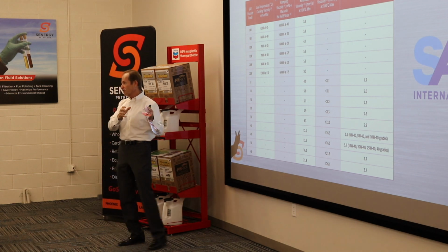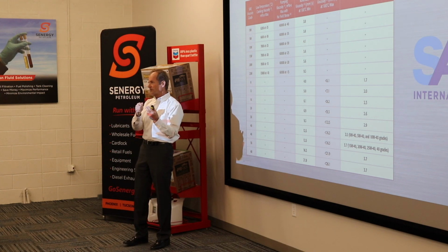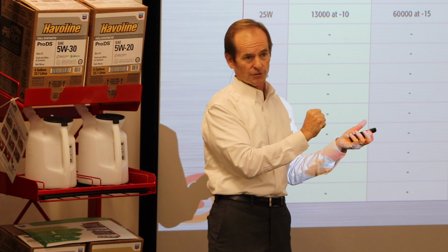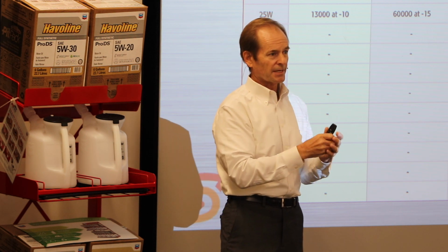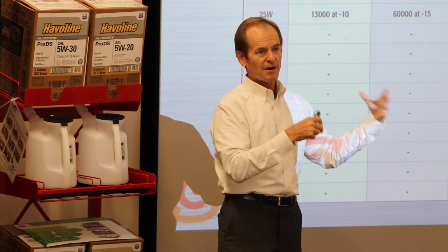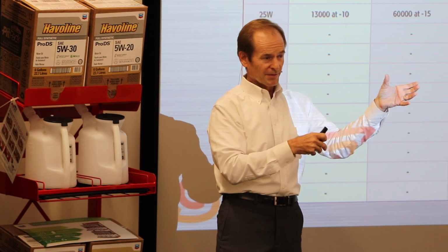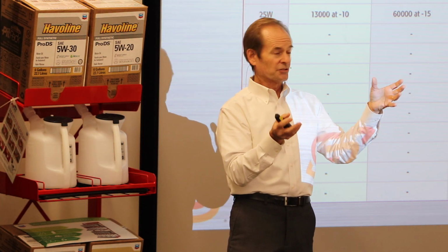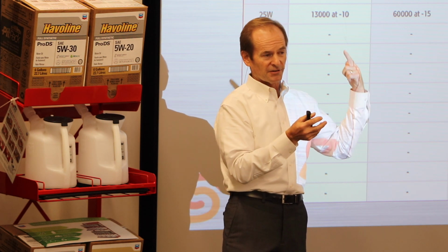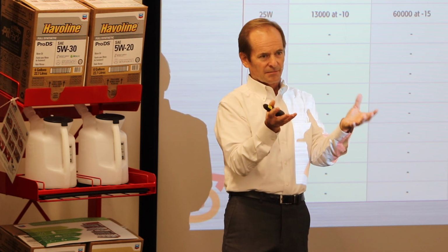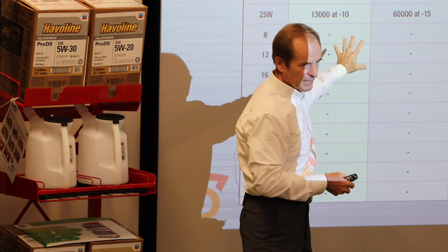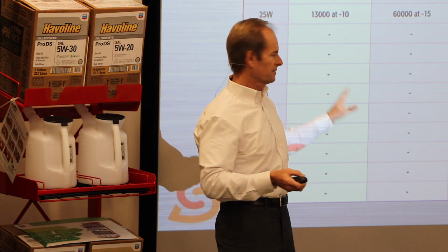The other one measures how hard it would be to crank an engine that's filled with that oil. It's actually called the cold cranking viscosity. Okay, those are 2 different cold flow properties because you could have one of them be real good and the other be real bad, and it would be a bad situation. So they just said, okay, we're going to make our W requirements have to meet both of these cold things. So they made the cold end a little more complex.